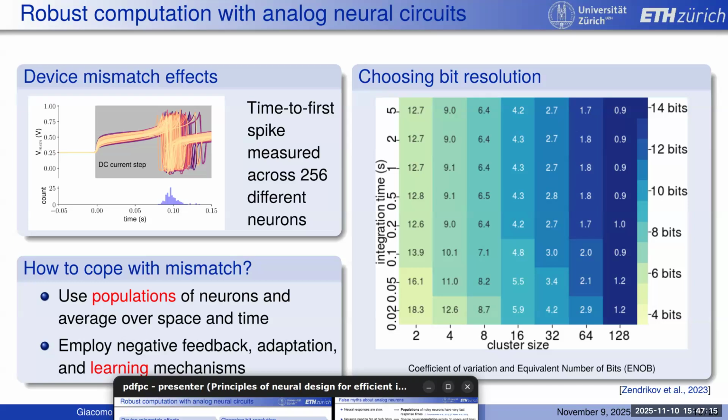What magnitude of temperature change are you talking about? It depends also on what you design. If you don't do anything, then the temperature actually has a huge effect. If you change it by only 2 or 3 degrees Celsius, you will see a variability in that range of 10-20%. But we can use engineering techniques. We can have temperature compensated bias generators. On the side of the chip, you could put something that compensates for temperature changes, which regulates temperature like we do in our body. And then you remove the dependence on temperature by having some brute force engineering.